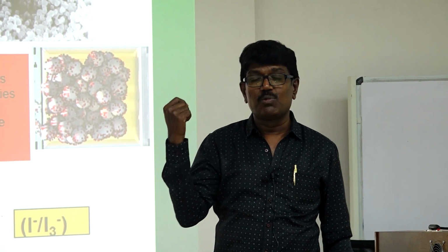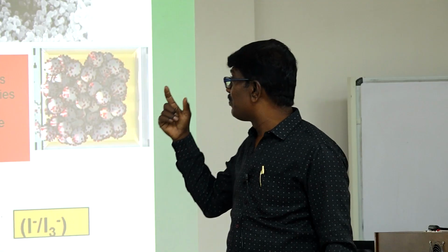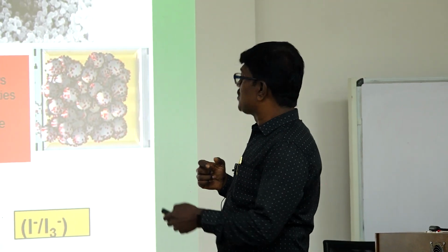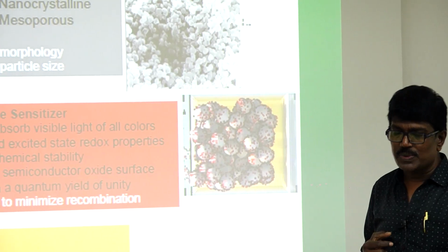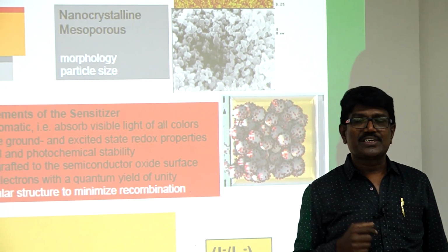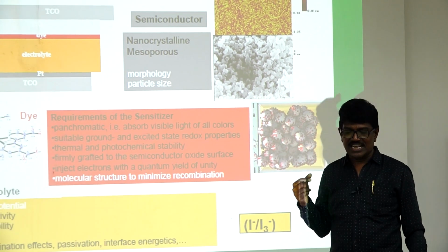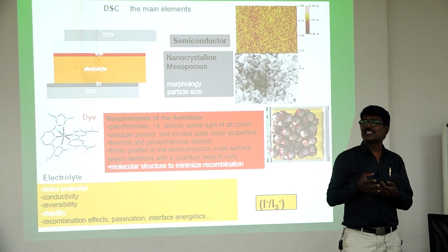And we will demo this one on Thursday afternoon, how to make the solar cells. Okay. So in this concept, first we have a TCO. TCO is called transparent conducting oxide glass. Transparent conducting oxide glass is a glass where a normal glass plate is not conducting.